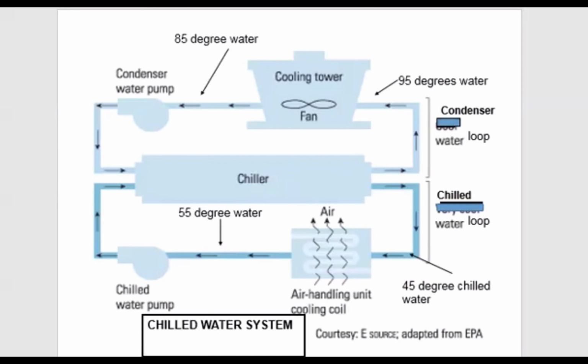All right, in that second loop below, and hopefully you can see it with this arrow, cool air is passed through around 45 degrees through this internal piping. Air is passed through here, and it's the blower that's being controlled by the HVAC system and the thermal unit. If we want 65 degree air, this continues to blow through there until the temperature reaches 65 degrees wherever the end of this ductwork is, and then it shuts off.